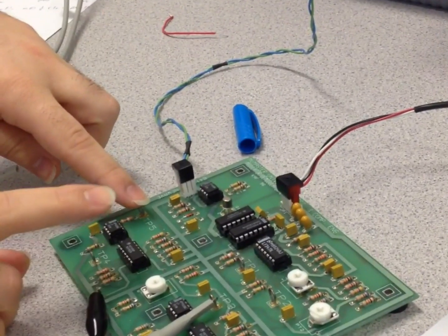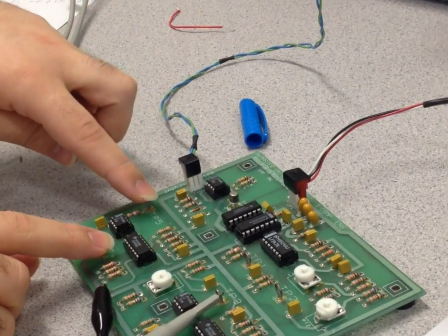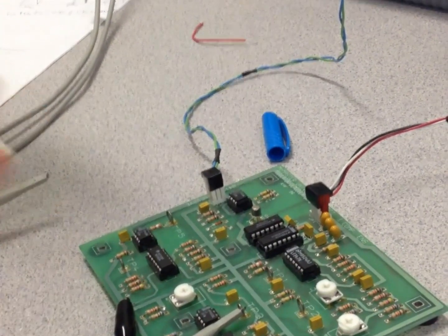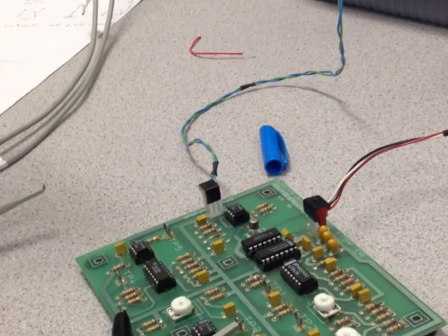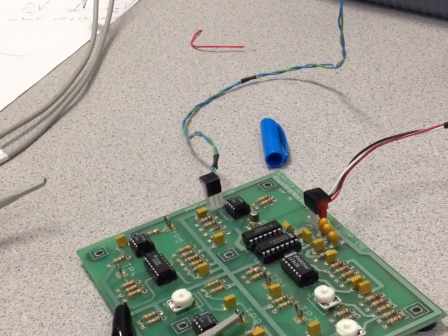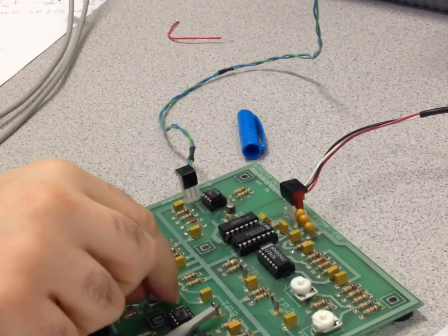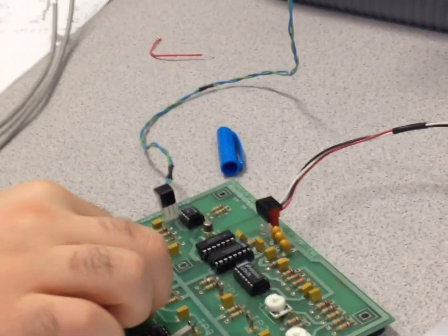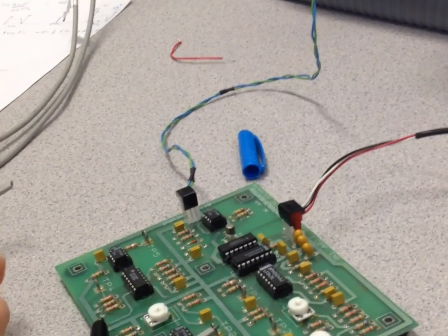TP4 and TP5 is the signal multiplied again by cosine omega c t in the receiver part and after the filter. As we see, the filter is not ideal, so we have our message, but we have some leaking components from the 64 kilohertz and its harmonic, not 64 only, but 64 and 128 kilohertz. These harmonics should be suppressed by using a better filter to get a good output and to get back your signal. You could adjust potentiometer 3 to make these peaks, which are the 64 and 128, as minimum as possible. As you vary this, you try to suppress these peaks as much as you can.